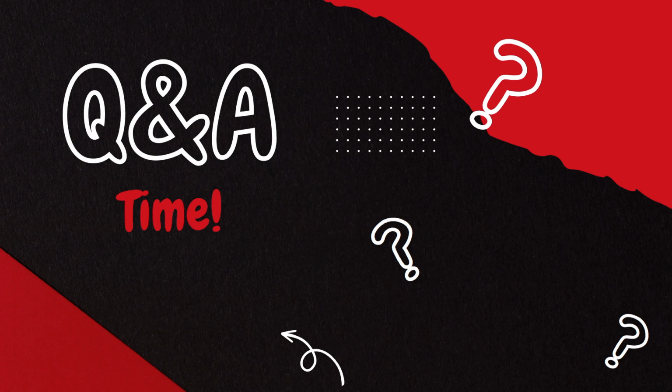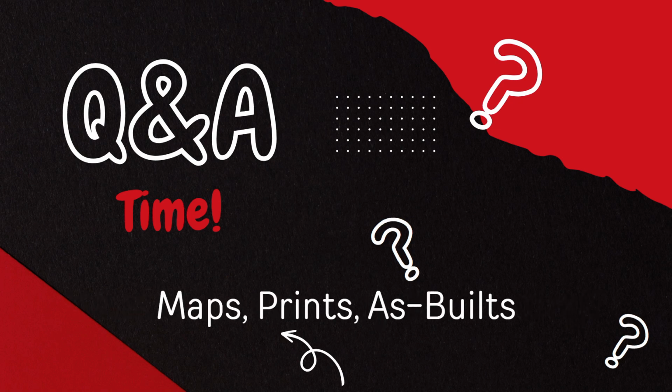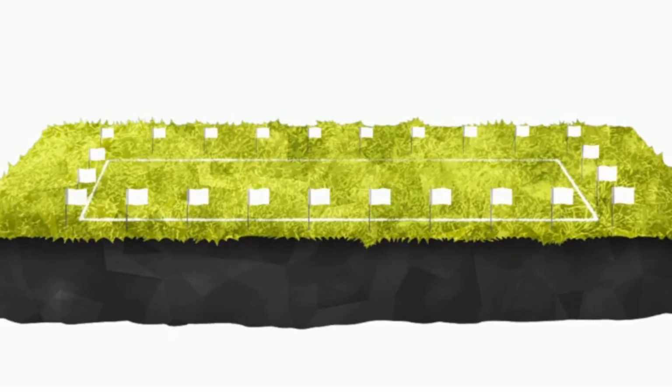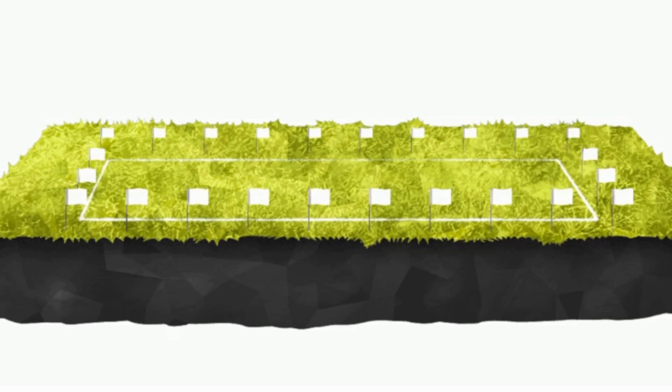So question for you. What is the first step for locating? It'd be maps, prints, and as-builts. You got to consult what information you have and compare it to the dig area that's already out there. Hopefully the excavator has white lined the area he plans on digging and put some white flags down. So you can take that and compare them to the maps and prints you have. And then you know exactly what needs to be located in that area.